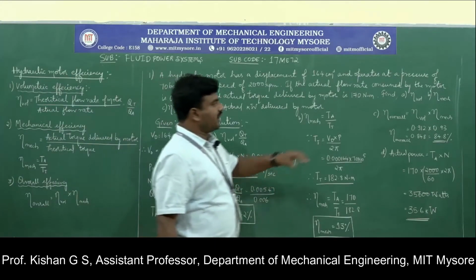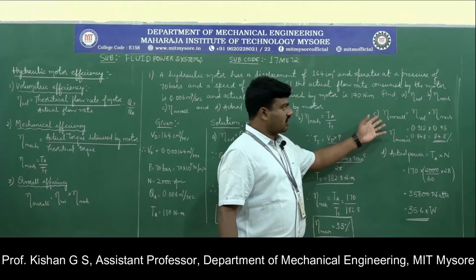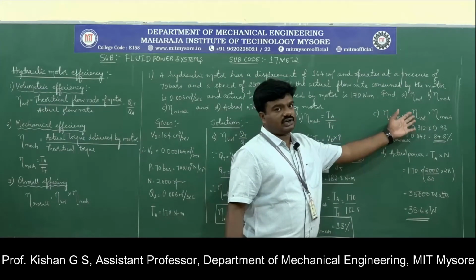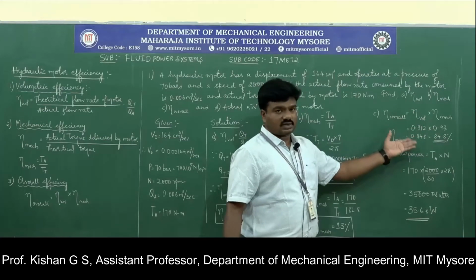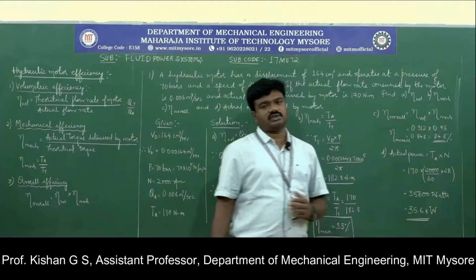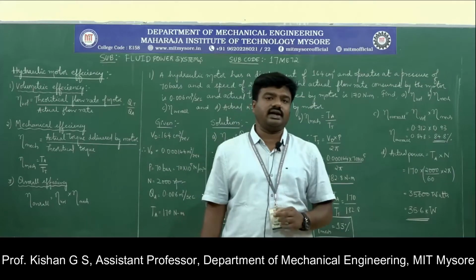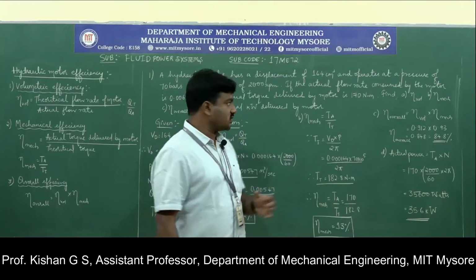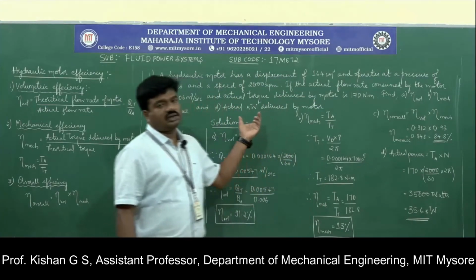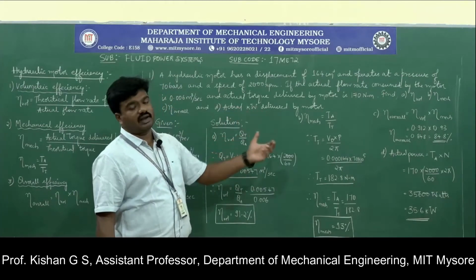Followed by the overall efficiency. Overall efficiency is volumetric efficiency into mechanical efficiency. With direct substitution, you are going to end up with the overall efficiency being 84.8%.